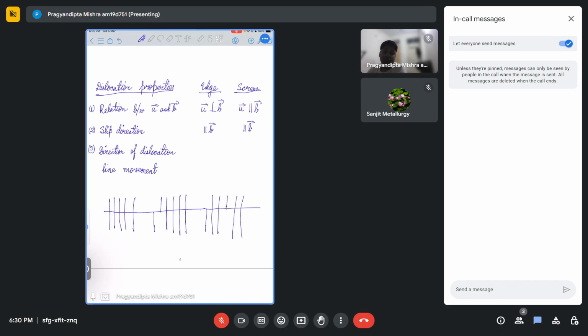Right. So the direction in which the dislocation can move is also determined by what kind of dislocation we are looking at. However, a dislocation can only move perpendicular to the dislocation line, right? Because the entire dislocation, let's say that this is my dislocation, this entire thing is the dislocation. I cannot move this in the plane of the dislocation line, right?